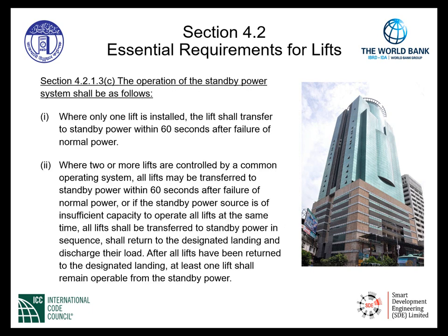The operation of the standby power system is specifically indicated here for the number of seconds that the generator must supply power. Item number 1 of section 4.2.1.3c tells us that where only one lift is installed, the lift shall transfer to standby power within 60 seconds after failure of normal power. Item 2 is where we have 2 or more lifts that are controlled by a common operating system. All lifts in this case may be transferred to standby power within 60 seconds after failure of normal power.